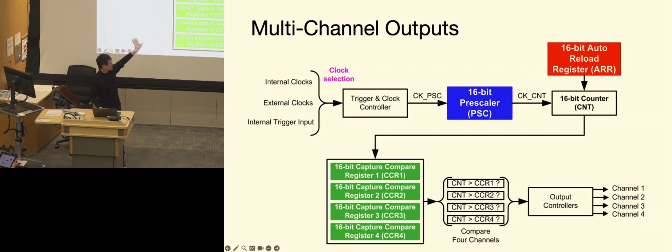This is a very high-level view of how these things get connected together before it goes to the software level. Basically, you have the raw timer signal coming in, and then the prescaler divides by 2, depending on how many flip-flops you have in the prescaler. Then you have the counter registers that give you even more flexible control and a continuous range of frequencies, or periods, which is the same thing, that you're able to choose from.